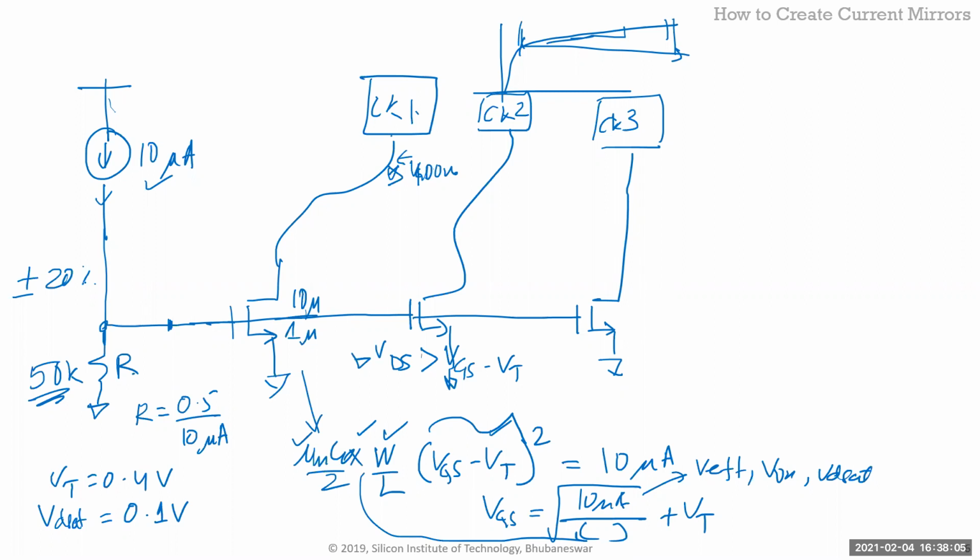Plus, when I'm doing this small current, you can see that's a huge resistor as well. And if it is one resistor, it's fine. But the biggest problem is that it will not match. So both for mismatches as well as process and temperature variation, the current will vary quite a lot. So that's the reason we don't generate the voltage this way. Okay, now tell me, how can you generate the voltage to remove this variation now?